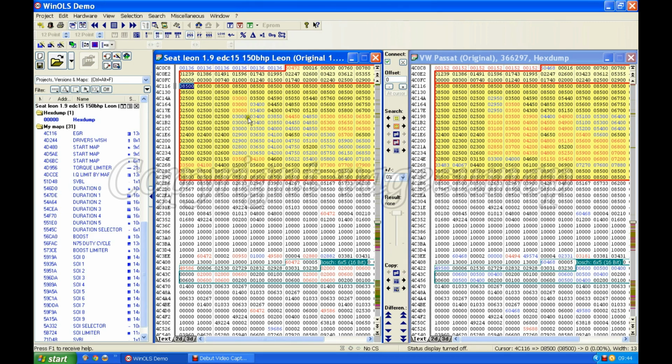Because if this value was dropped a fraction, it means that the actual EGR value for the flow rate has increased very slightly. Remember that although this is called the EGR map by most people, it's really the mass airflow map. So if the mass airflow has dropped slightly, then the EGR value here has increased very slightly, and it is very slight. So I suspect the difference between the two is something to do with fueling, but something that we don't know.